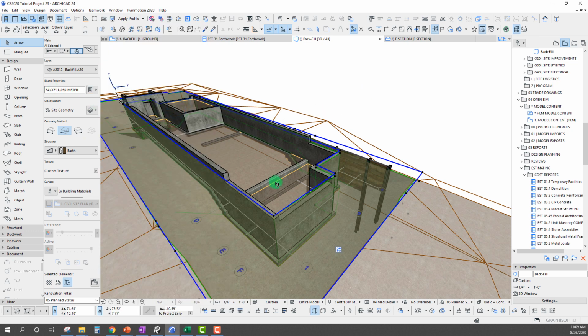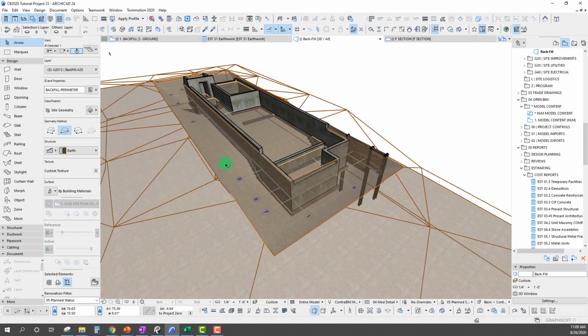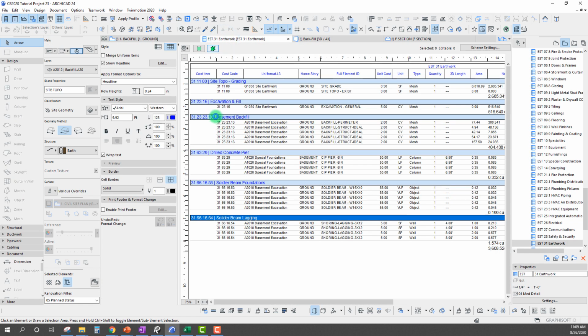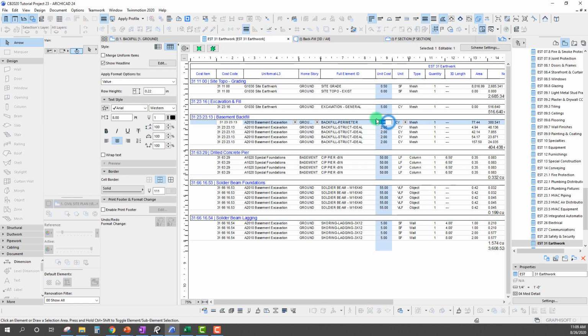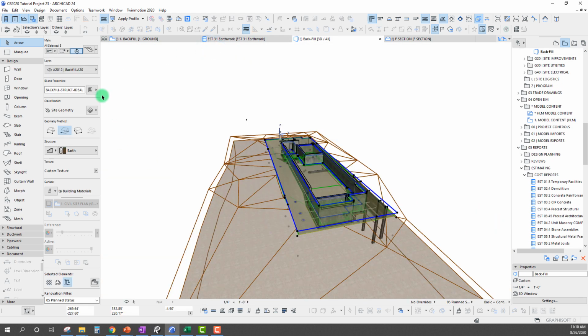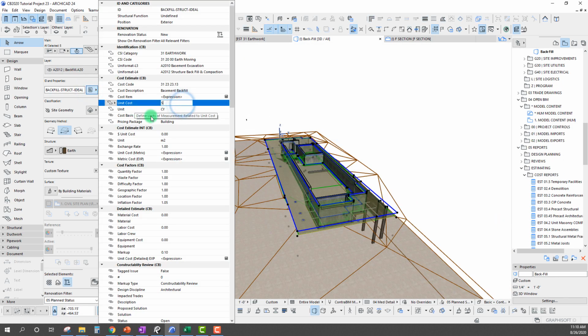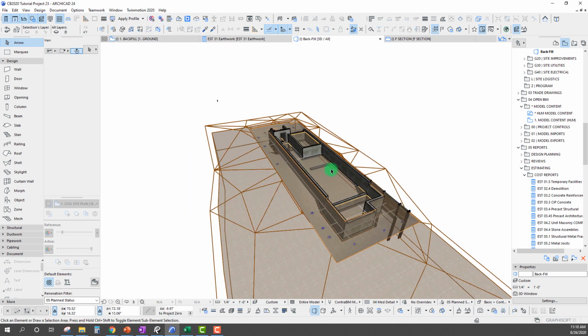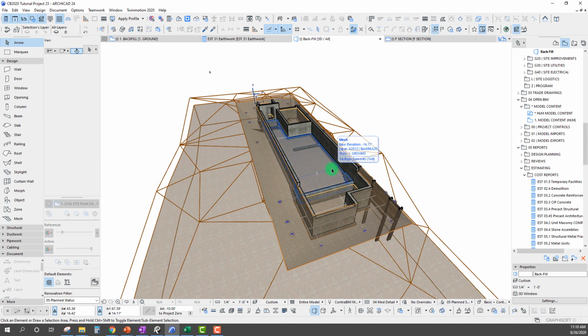So one thing that I'm thinking that we definitely want to adjust here is going to be our backfill cost. So this to me seems it would probably be $2 maybe a cubic yard just to put it back in place, but then you're going to have some compaction that is needed. So I would say across the board here we can probably set this at least like probably $5 a cubic yard, just to make sure that we are covering it with the compaction. And so let's go ahead and run this and see how we are looking.